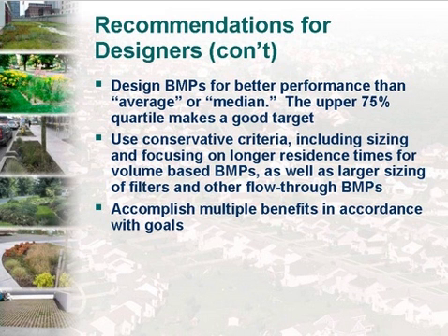And so what we have suggested is look at that 75th percentile pollutant removal and design around that for your BMP. And a practical way of perhaps approaching that, for instance, is to look through the studies and examine the ones that have gotten a little bit better than the average or median performance, and see if you can discern any design details that might have led to that better performance. So I think that's one use for all this information that we're trying to compile out there.